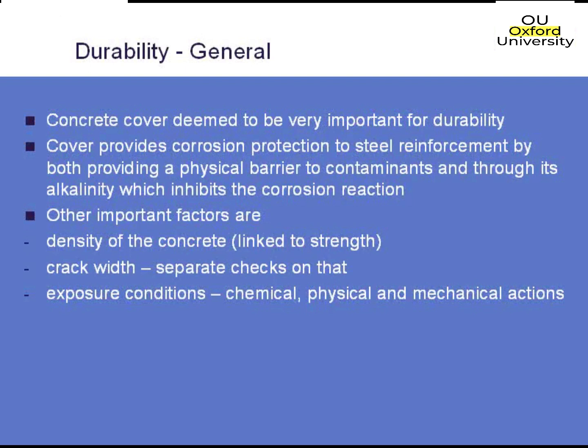A good amount of cover also gives corrosion protection to the reinforcement by providing a physical barrier and through the alkalinity of the concrete itself, which again helps prevent corrosion occurring within the reinforcement. There are some other important things to consider as well, and these include things like the concrete density. Obviously, the denser the concrete is, the better your cover is going to be, and the more ability it's got to prevent contaminants getting to the reinforcement.